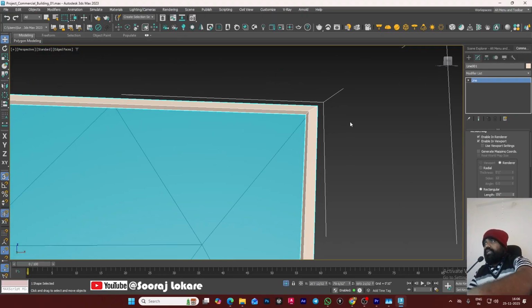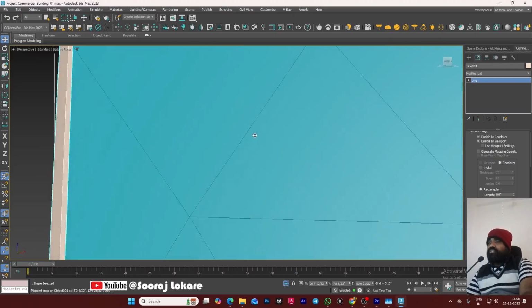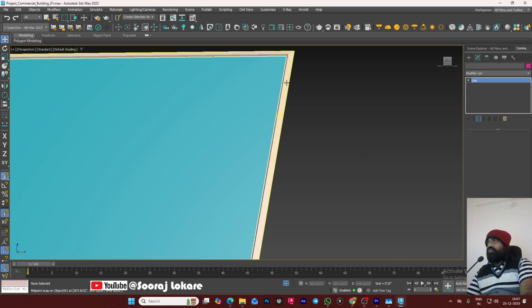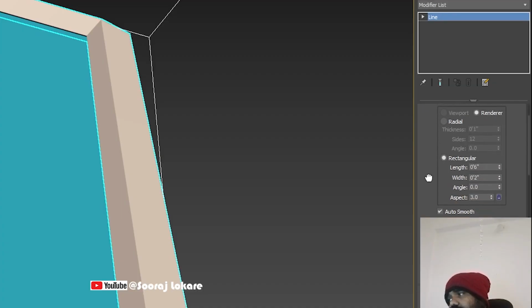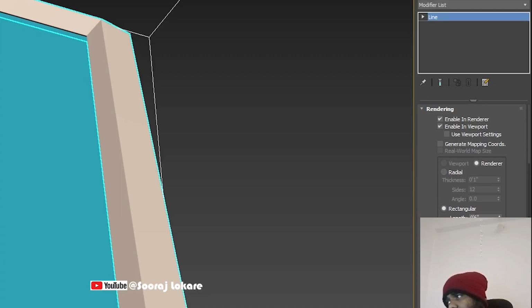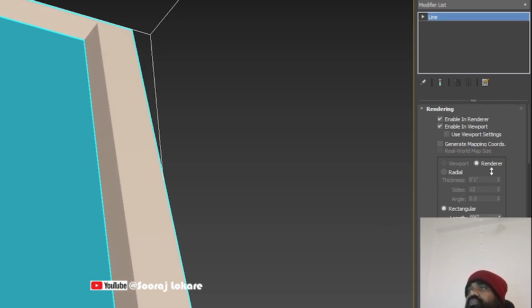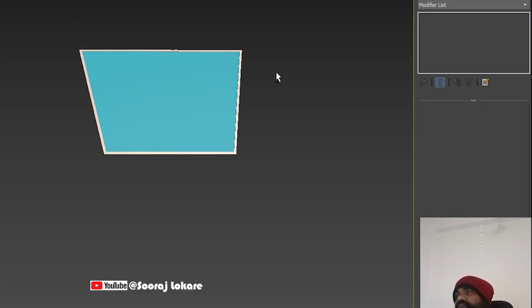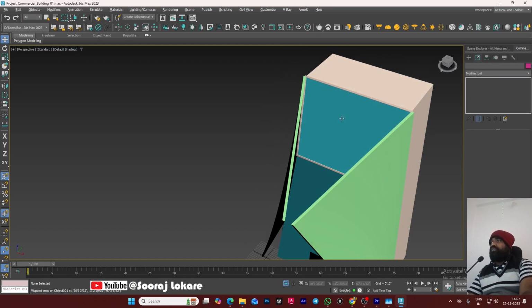But as you see, the direction of the framing, is it good? No, I don't think so. So I think you should change the direction of the framing at some point. So how to fix it? In the rectangular option you would see an option here, angle. If you just minimize the value, yes, we got a proper framing here. That is something we need to fix first.